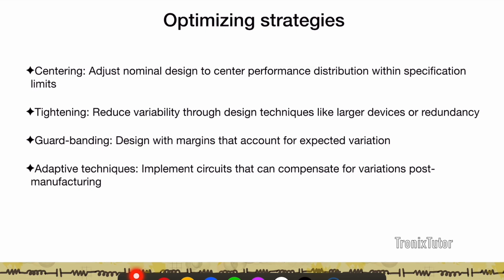So to summarize, Monte Carlo is a very important technique. It's used very, very commonly in the industry, and it's a useful tool to understand the limitations or the performance that you can expect from your manufacturing process.